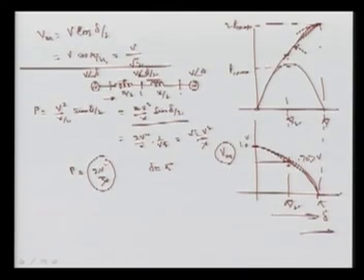Now what is happening? You can see here there was some stability problem, meaning it was not possible to load the power system more than this 90 degree angle, that's pi by 2. We always load below this because if there is some surge or transient, the system will lead into the unstable zone. So we can go maximum in steady state up to this point. Now we can go twice of that, and here all the region is stable, whereas here it was not stable beyond this. So we have increased the steady state power transfer limit of the system to twice the P max value.